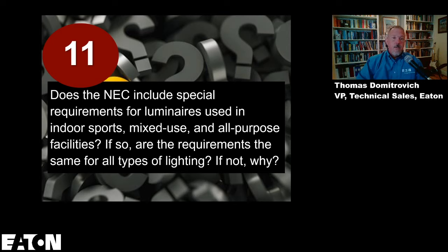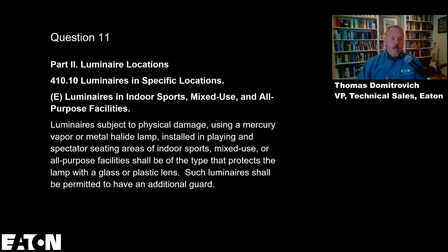Let's take a look. So if I look at part 2 in Article 410, remember, 410 is luminaires, lamp holders, and lamps. I'm going to 410.10 luminaires. So part 2 is titled luminaire locations. Part 1 is general. Part 2 is luminaire locations. So you would think that that's exactly where you need to go.